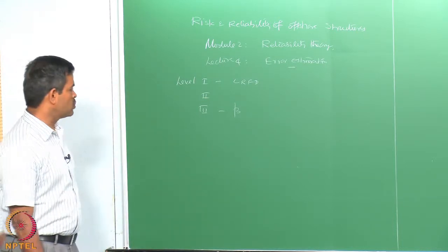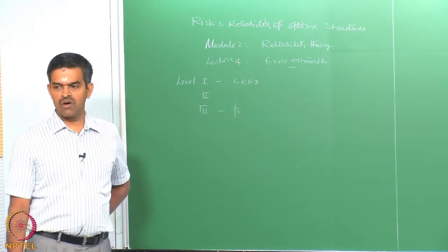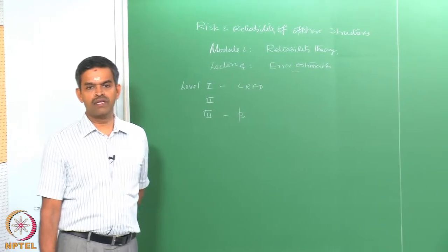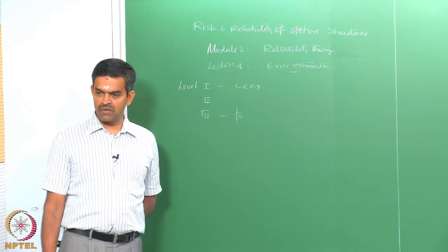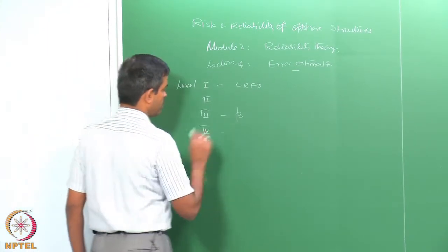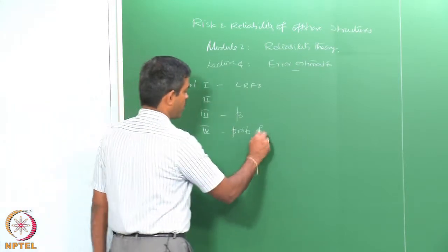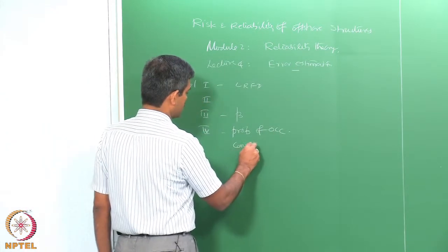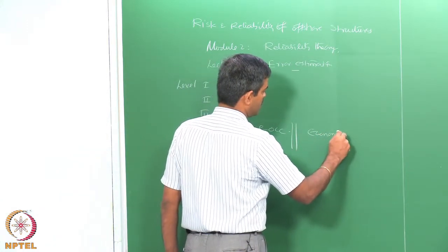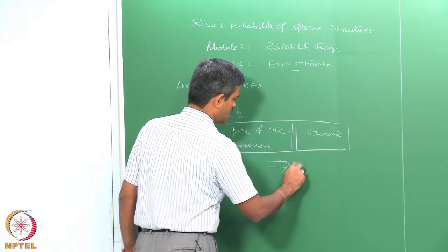Level 4 of course includes engineering economics in the whole analysis under uncertainty. It considers cost and benefit of construction, it considers maintenance applicable for repair and other studies. It of course extends the study to understand details of consequences of failure. Now level 4 talks about the probability of occurrence of an event which is undesirable as well as the consequences, and it also addresses, interestingly, the economic perspective of this. Therefore, in level 4 the reliability analysis actually converges towards risk assessment.